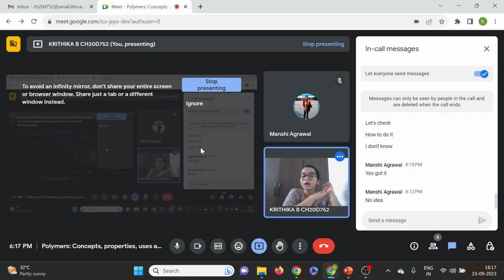These are two types of failure that occur when you use an adhesive. It can be cohesive failure or adhesive failure. When you see only the adhesive on both the surfaces, it is a cohesive failure. The adhesive molecule has ripped apart. Whereas when you see some open metal surface or open wood surface, for example when you have joined some wood and paper and you see some open wood surface, then the adhesive has not actually stuck to the surface properly. Then it is an adhesive failure.